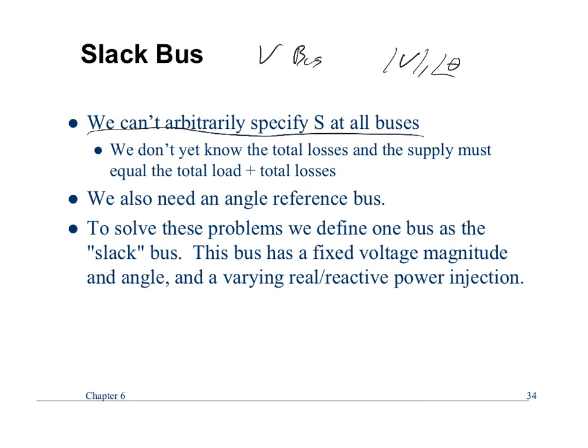Okay, to make it solve, but the only problem with that is in the real world, you have to have the P and the Q supplied. So if it's a fictitious bus, the P and the Q need to go somewhere. So you must have some intelligence in terms of a fictitious bus, saying this is pretty close to a lot of generation, so I'll put a fictitious bus here, and then I'll balance things out in that local area, perhaps, is what I'm guessing.